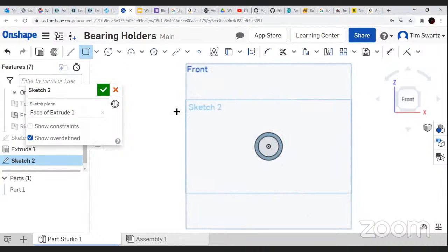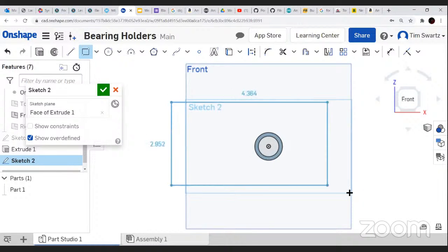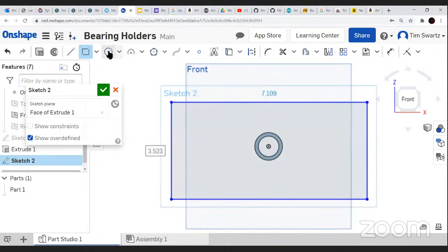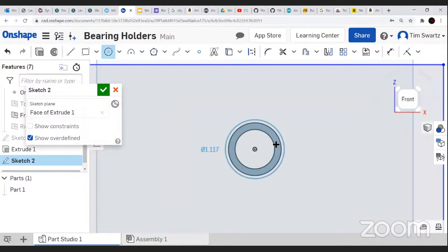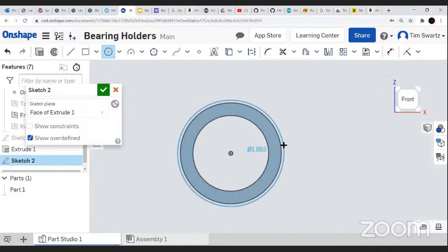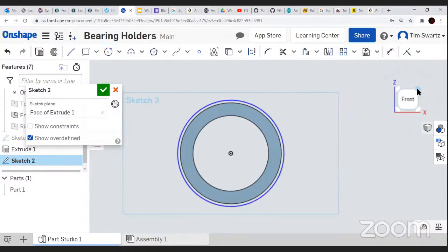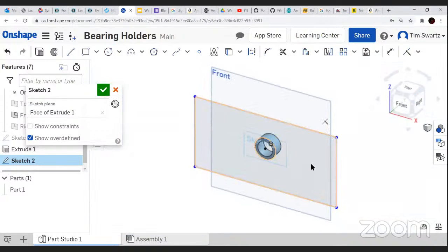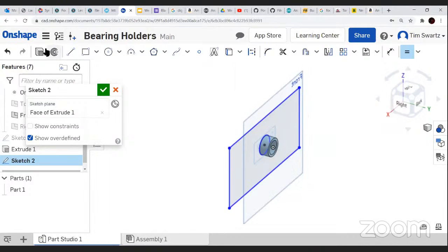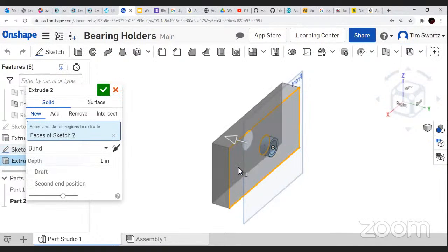We're going to have this be part of our body here. And we're going to make this hole just slightly bigger, something like that. And that way, our part, I'm going to extrude this. It's not going to be the actual shape of our foosball table, but if this was a small cross-sectional view of that area, this is probably going to be 0.25.